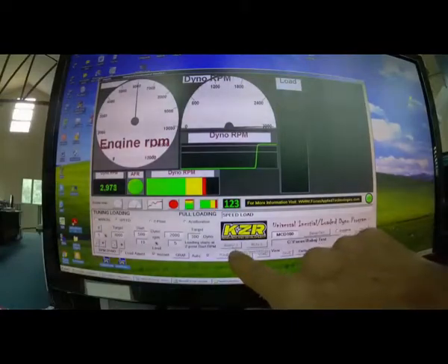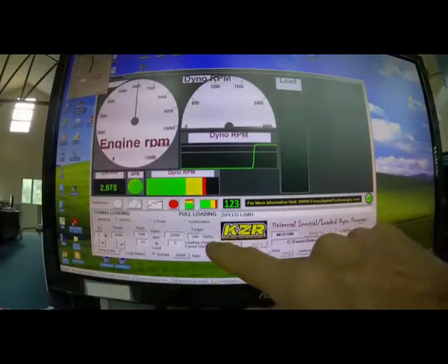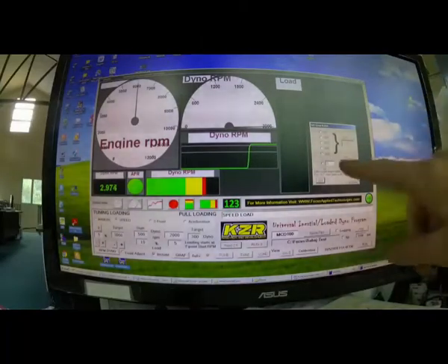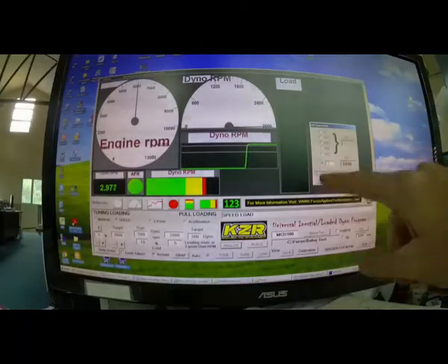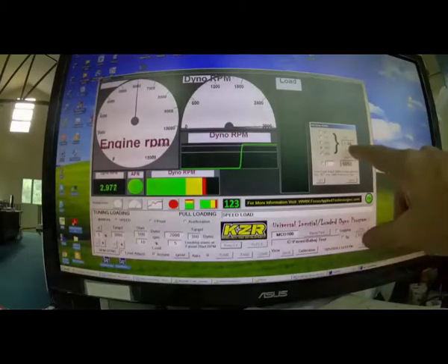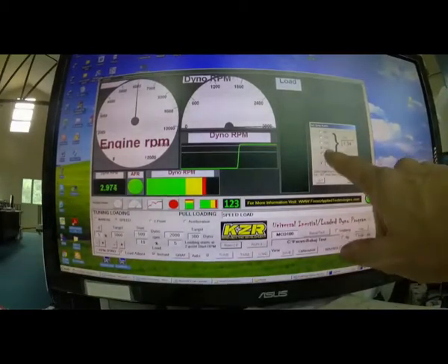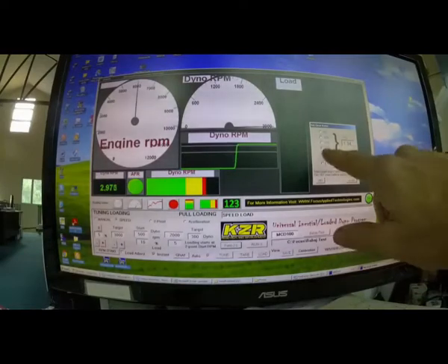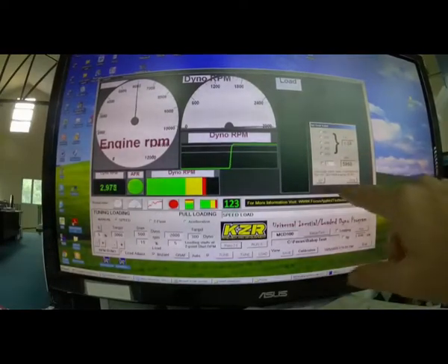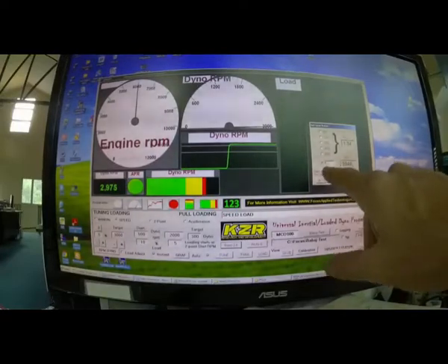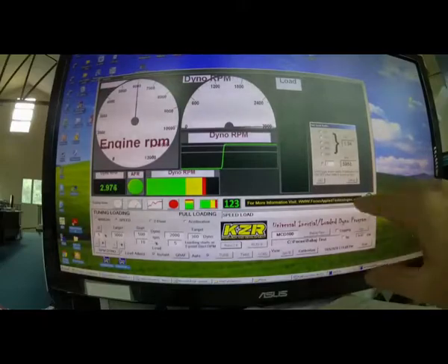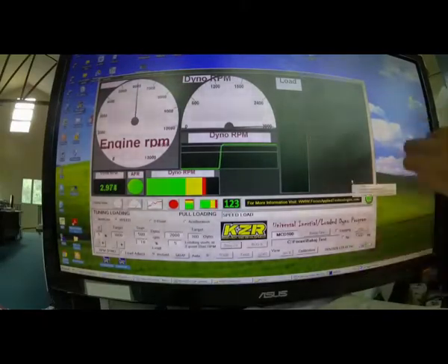So if you click on your gear ratio box, you get this guy, and that allows you to set up your gear ratio. Either you can pick it as 2, or for example, I could pick that I want to spin at 4,000 RPM. If I'm running my engine at 4,000 RPM, then you set your engine at 4,000 RPM, and that gives you your gear ratio, and then you click on here to set it. If you want to set it to a given gear ratio, you put that gear ratio in here. It shows you what the calculated RPM is, and then you set it. Or in this case, I'll just cancel because we've got it right.